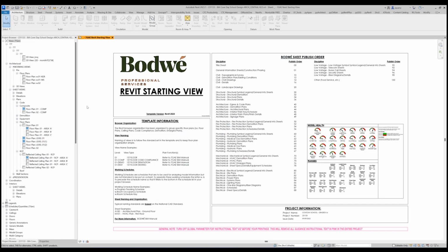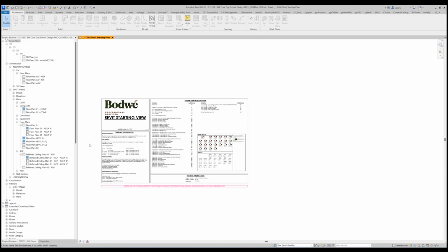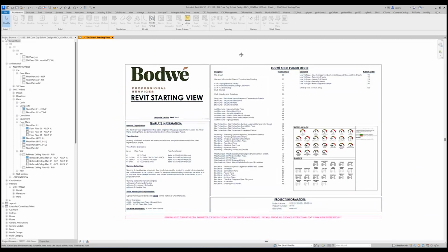Whether it's a knockdown frame or a borrowed light hollow metal frame, they're usually building it in pieces. Even if it's prefabbed, it's still pieces, right? So I use that for everything: hollow metal, aluminum, and any other light generic window frame type. In plan, all you're caring about at 1/8 inch is the 2 by 5 3/4 depth, or if it's a curtain wall, it's 2.5 by 7.5 deep, right? Other than that, you'll see here how this works.